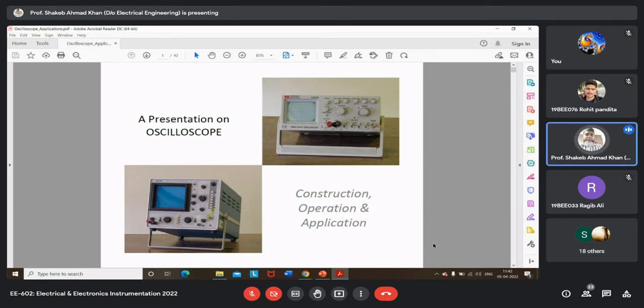But in digital oscilloscopes, it is possible to capture a frame, a screen of the oscilloscope. That is called stationary mode, meaning it is not running mode. As far as stable display is concerned, this is a very important thing that you should keep in your mind: the oscilloscope can display only periodic time varying signals.